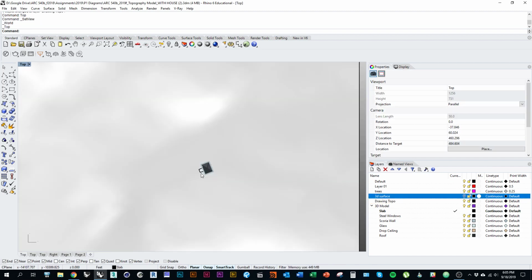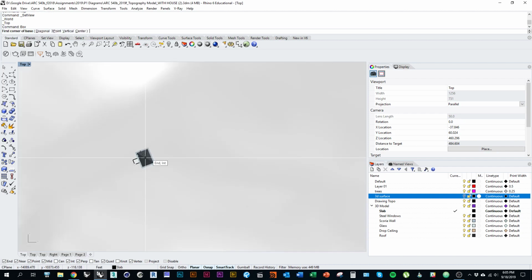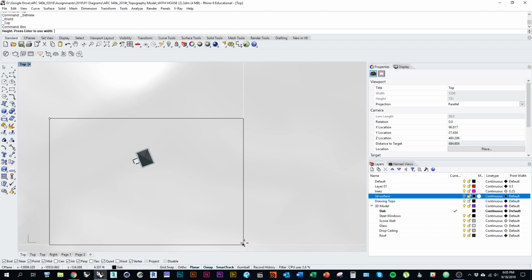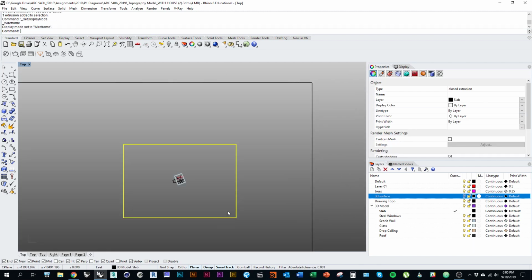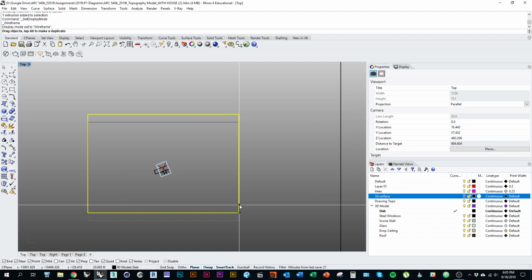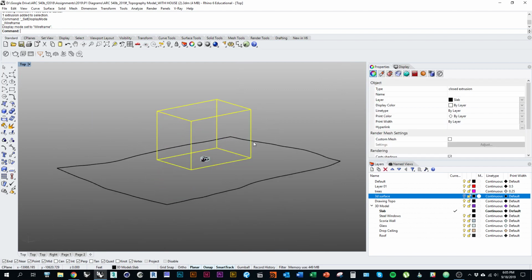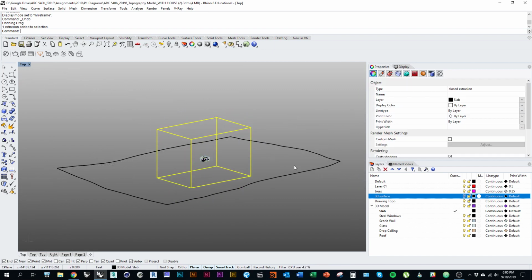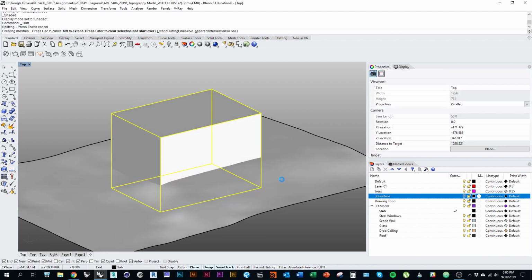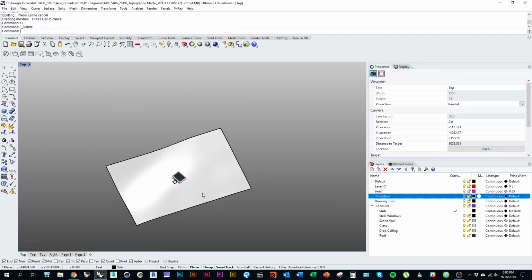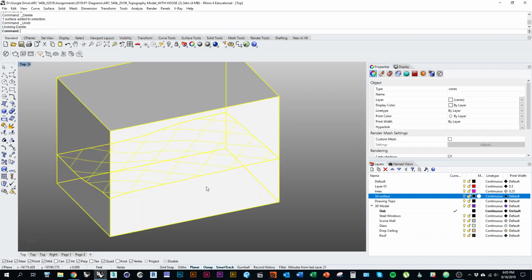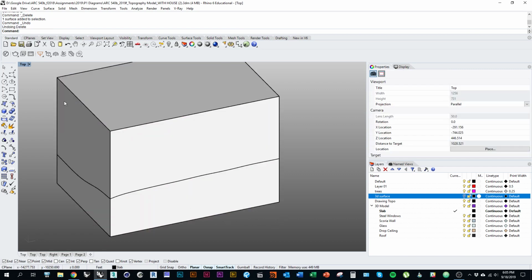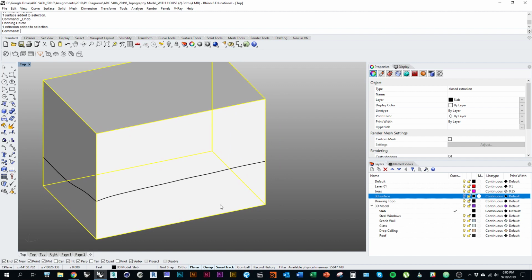Now if I go into top view, I can also make a box. I don't need a ton of topo information around my house for the drawings, just a little bit. I'll maybe trim it down to something like that. Oops. And then you can drag it holding Control on the keyboard to only move it vertical. So I'll have it intersect my surface, trim my surface, and then delete the box. Actually, before I delete the box, I hit Control Z or undo. I also want to make some contours with this thing.